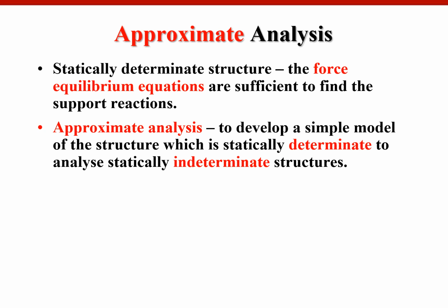If you have three unknowns, we can apply the force equilibrium equations, which are sigma F sub x must be 0, sigma F sub y must be 0, sigma moment about any point of the structure or free body is 0. So we have three equations, so that if you have three unknowns, it's enough to solve for three unknowns. But if it's more than three, then we need one more or two more equations. We call those structures indeterminate structures.